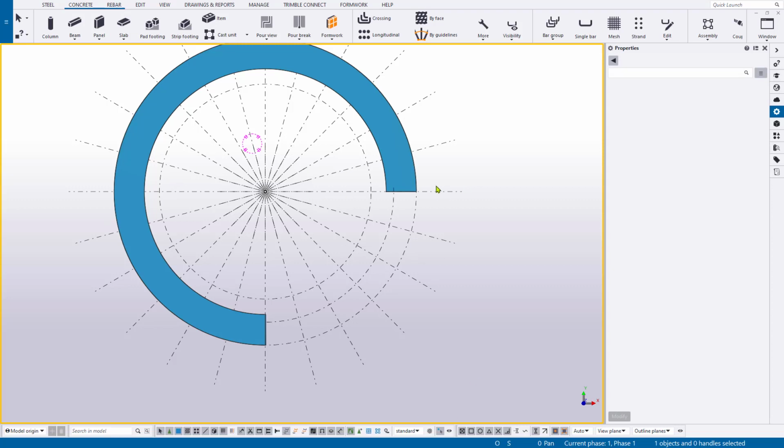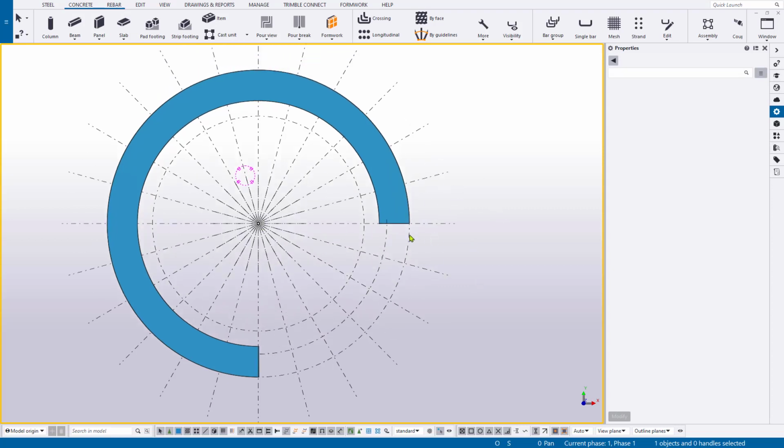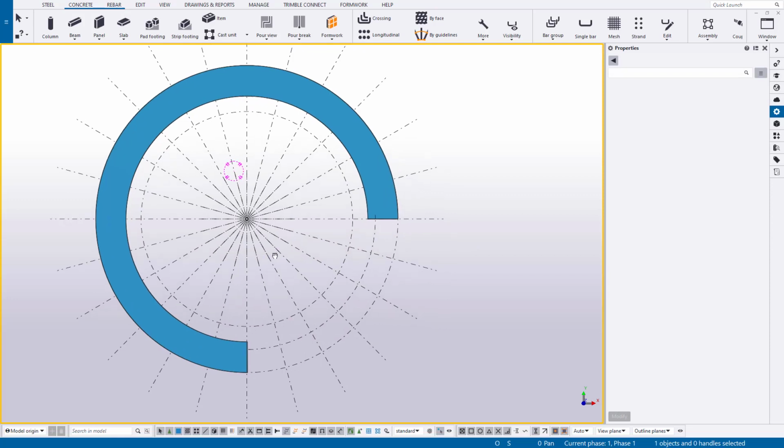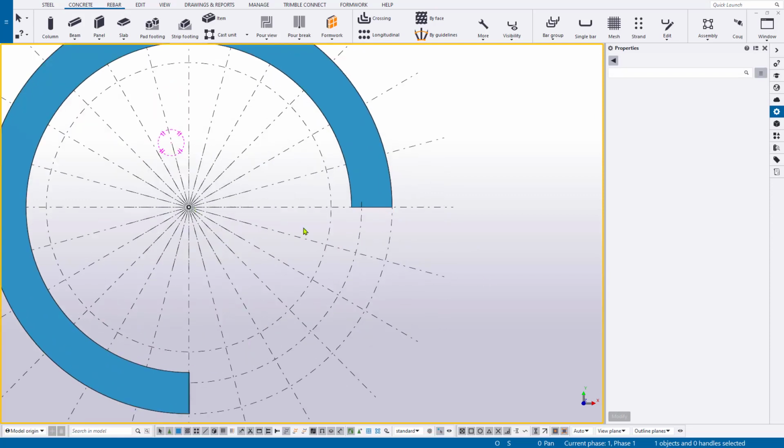That way I just model here and then rotate into place, whatever degree it may be, either a nice even one or fractions or decimal points of a degree. It's a lot easier to get something correct on an even plane and then put it into place. So that's why I chose those clicking points there.